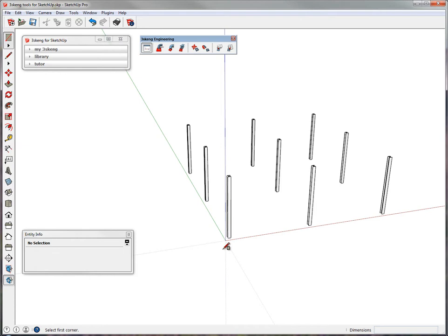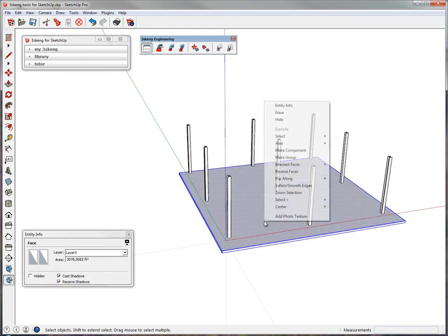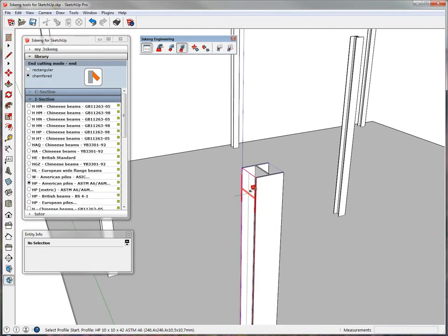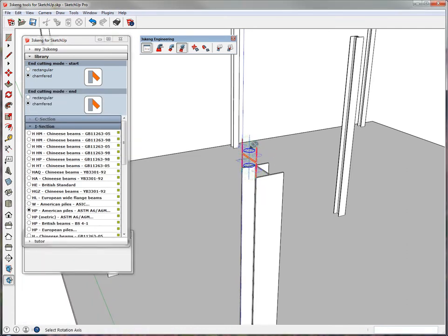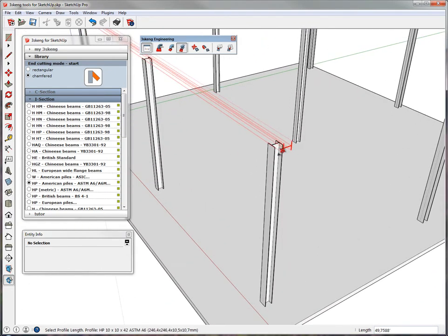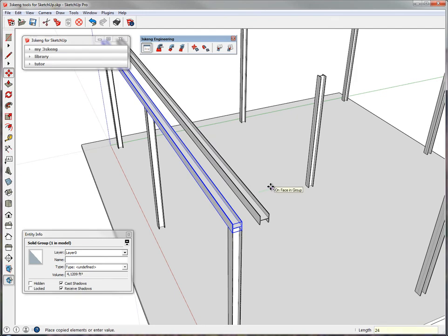Now we just give our small design a floor. To add a beam on top of this one, we just click the tool and select the direction we want to have it. In this case, it will lock exactly if you are adjacent to the top of the existing beam or if you want to be on top here. By clicking, you confirm. Here, you can select the chamfered beam, which doesn't make any sense here. So by clicking escape, you can just roll back one step. And now we can catch the length. As you can see, this is quite easy.